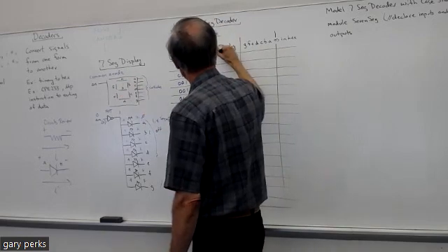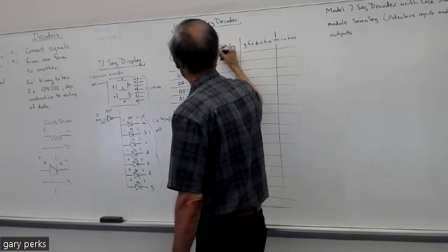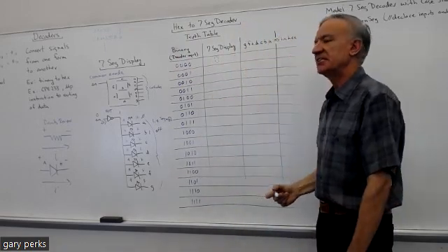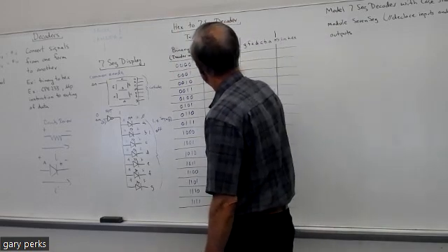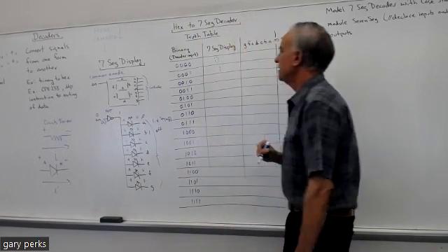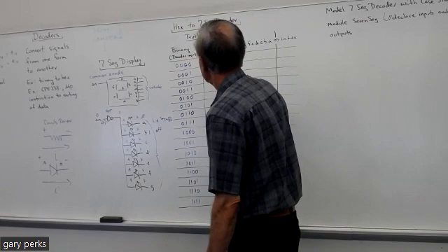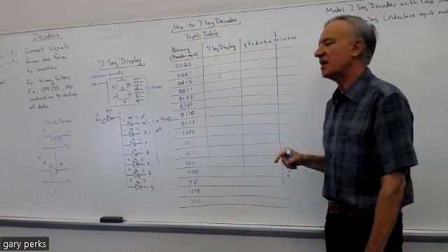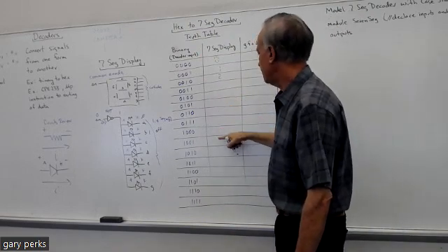That means I want the A segment lit, the B, the C, the D, the E, and the F. The only segment I don't want lit to show a 0 is the middle one, G. To show a 1, I just want B and C lit. To show a 2, it would be these segments. And you could keep going, 3, 4, 5, 6, 7, 8, 9.